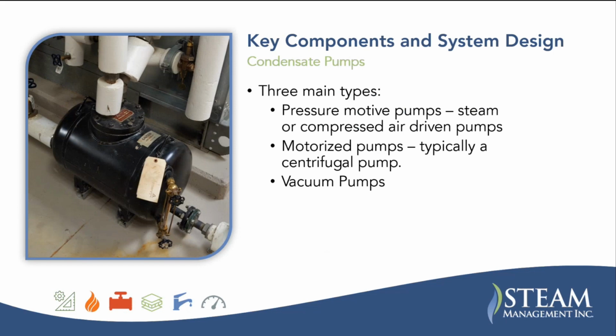Condensate pumps. There's 3 main types. There's pressure motive pumps or steam motive pumps. I usually say pressure motive pumps because sometimes they're configured where they have compressed air as a backup pressure source for startup or when steam's not available. Generally, they're going to operate off of steam, though.